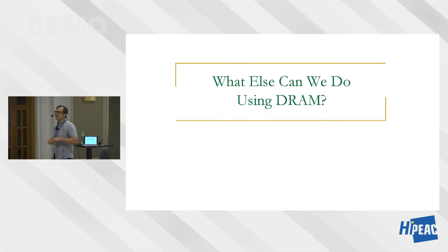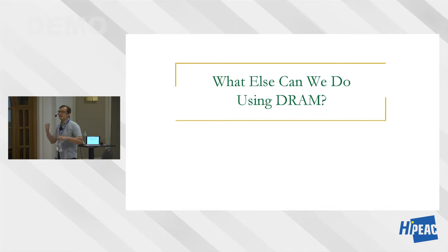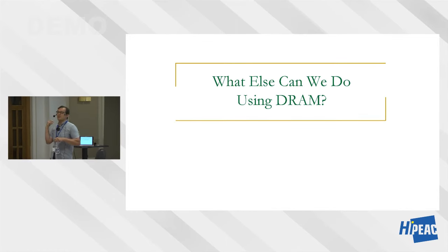But I think the effort to overcome that is changing the sense amplifier and changing the row decoder such that they're more robust in the way we're doing things. Right now, truly DRAM is not designed for this purpose, right? We're really violating the timing parameters so that we get a good timing to show these operations. Even these operations that we showed are not based on the perfect timings, right?